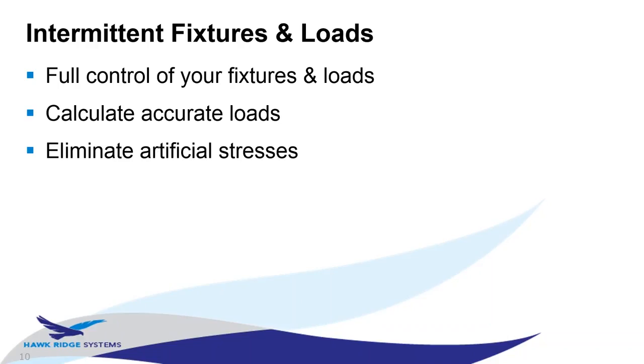This allows us, if we have a process, for example, a clip that opens up, puts in, undoes, and so on, to analyze the stresses in different stages, and you can get rid of artificial stresses that are induced by loads or displacements that shouldn't be there at a particular stage.